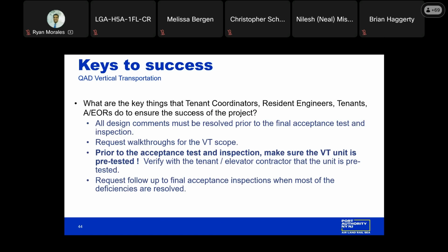We recommend conducting walkthroughs to ensure project compliance. For larger projects, cyclical walkthroughs are advised, while for smaller projects, they can be scheduled as needed. The walkthroughs provide an opportunity to identify installation issues that may not meet code requirements, such as presence of non-elevator related equipment, wiring, or pipes in the elevator machine room. Additionally, walkthroughs help us become more familiar with the site.